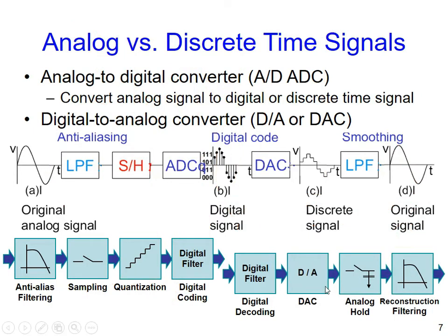Why do we need to make it discrete in the time domain? Because if you don't, it is continuous in the time domain. It means for each period, never mind how short the period you would like to process, you need infinite memory to keep the content. It doesn't make any sense, right? So we need to make it discrete in the time domain.